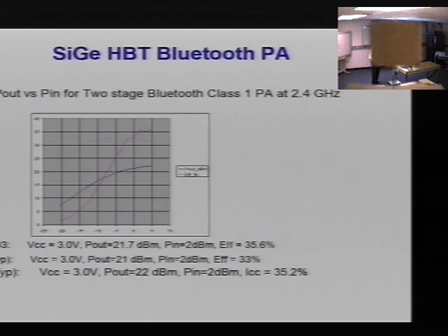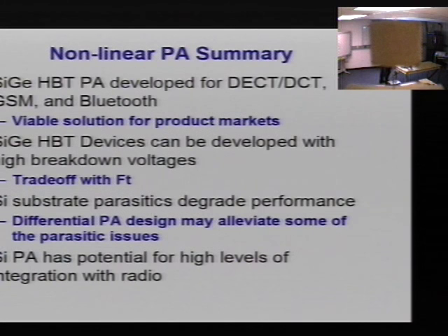Exactly. So we had to design for what all these other guys had, so we tried to match those specs for SiGe and Maxim. This is a little bit harder problem. For a differential PA, one has to be very creative in designing a high-power balun. There are companies and universities that have done some interesting research on differential PAs and baluns, and I really think there's a lot of room there for creativity.